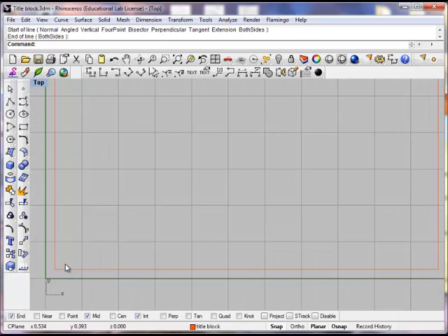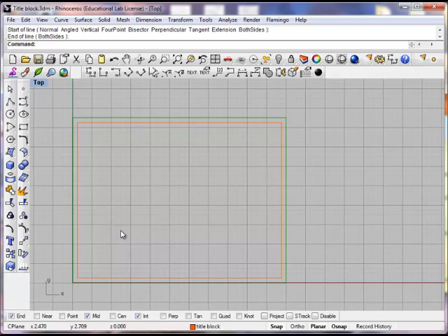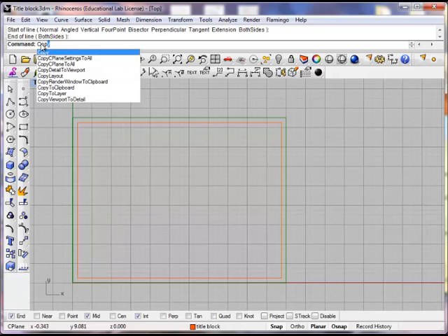What we want to do down at the bottom is set up our title block, which is 3/8 of an inch. We're going to use a new command called copy. It's not like copy from like a Word document. We're going to actually type it in, although Control C and Control V does work, but that doesn't give us the specific details that we want to use with the command copy that's embedded into this program. So type in copy up at the command prompt up here. Remember, as soon as you start typing, it recognizes that you want to key into the command prompt.